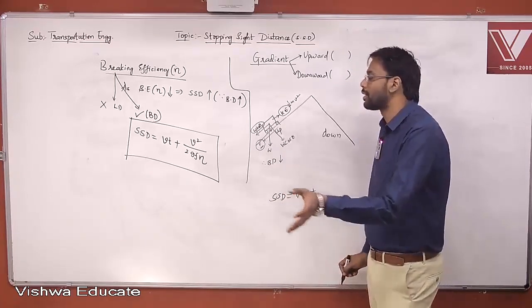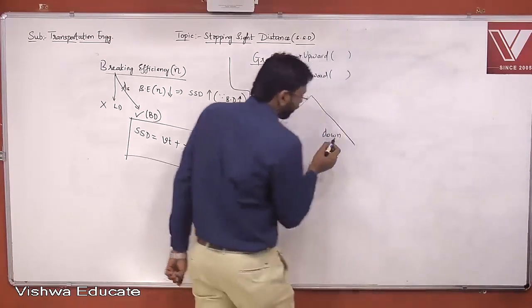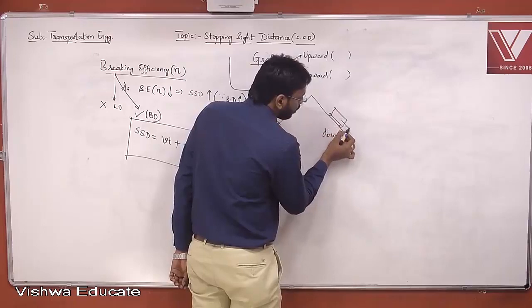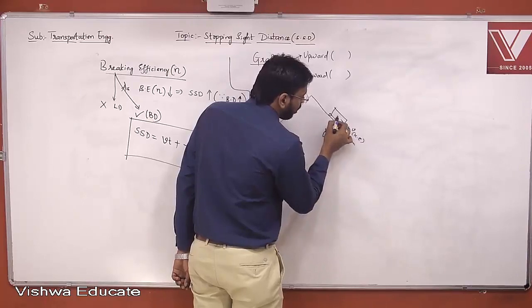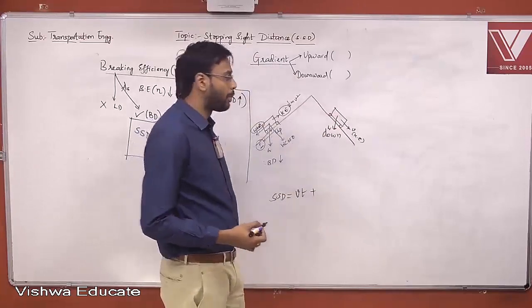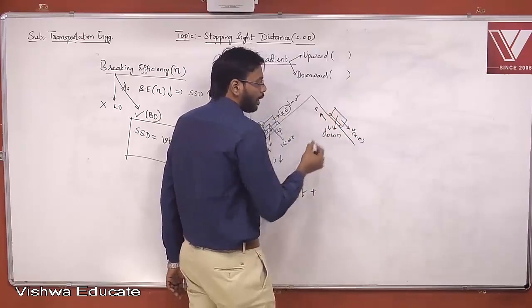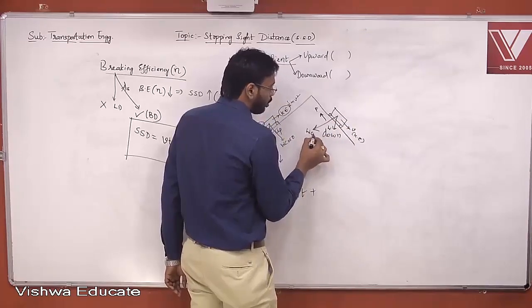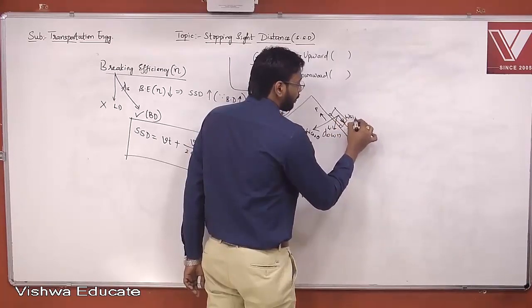If you apply a brake, the vehicle stops quickly. Whereas now, just consider a vehicle which is traveling on a downward gradient. So this is my speed, or this is my kinetic energy. This is the self-weight of the vehicle, right? Now you have applied a brake, so as it is moving in this direction, there will be frictional force here, and it has self-weight, so it has the same components, W cos theta, and this is W sin theta.